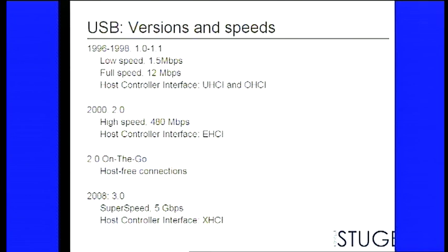Around this time, there was also a specification for the host controller interface. So the host controller is the actual chip, the PCI chip, or whatever bus it is on, that implements a host. And there were two standards, which was a little bit silly, but I guess the companies involved competed, and they each wanted their own. So there were two host controller interfaces, and this is a programming guide. It's a register specification for how you program a host chip.